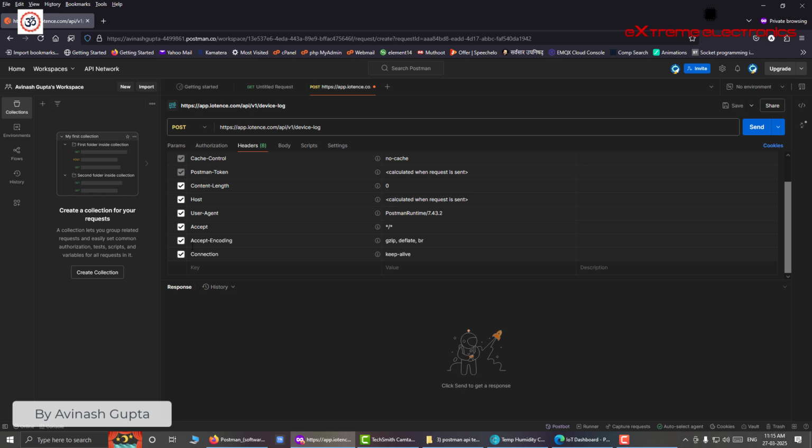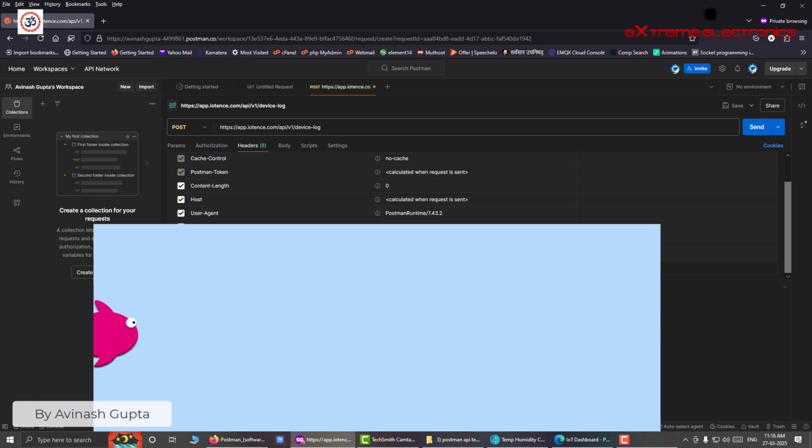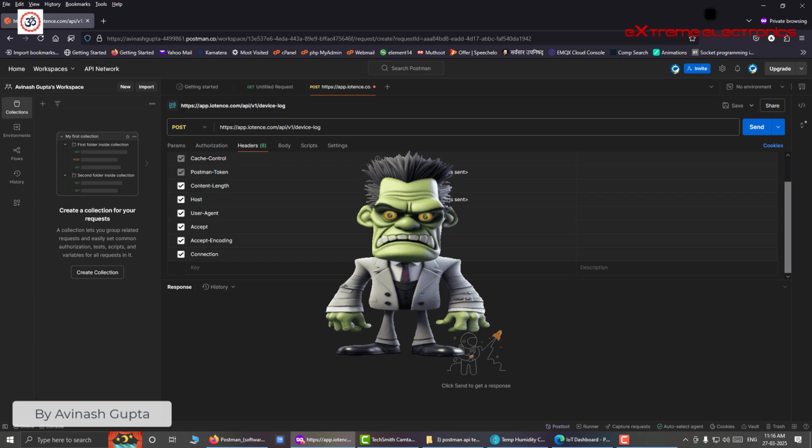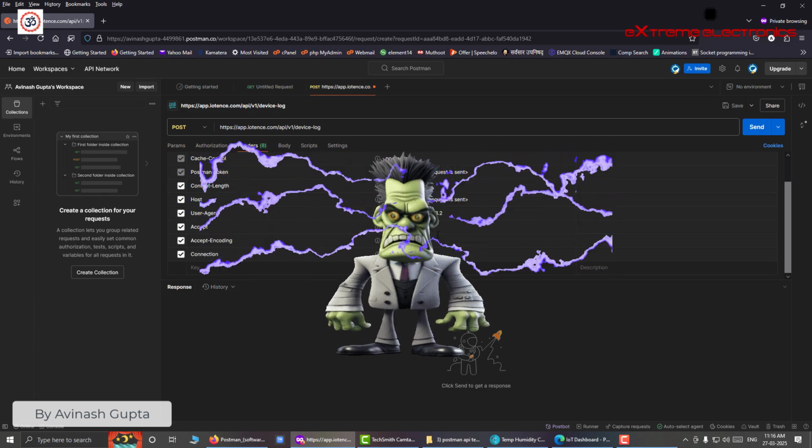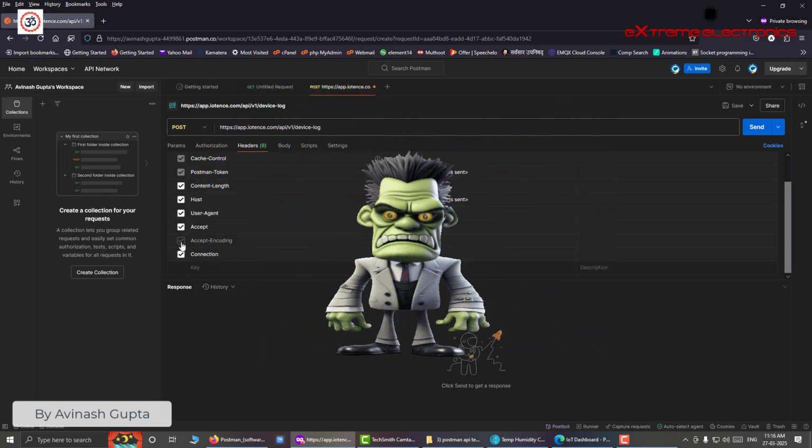And then they are using this compression also. You can remove this compression also. Generally, when we send a request from our embedded device, we will not use any compression. The compression is only required when we are transferring large amounts of textual data. But in case of this small machine to machine communication, this payload data is extremely small, so we don't need all this overhead, and it is very tough to get compression running on a small embedded device. That is why we will skip this.